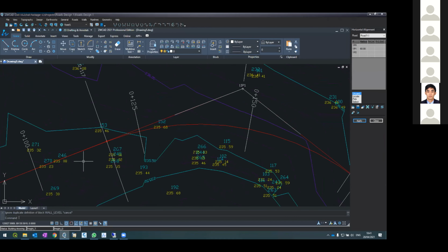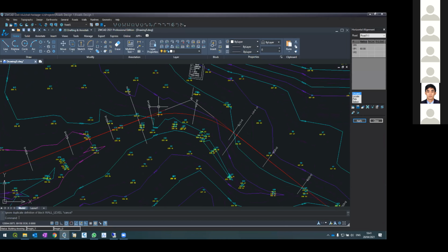Definitely, if it's a small road inside urban and there are houses here, there's no problem to change by 60 meter. It's a regular curve because you're driving here at a speed of 40, 50 kilometers per hour maximum. What I want to say is that the bigger the curve, the faster you can drive. So there are regulations for it.